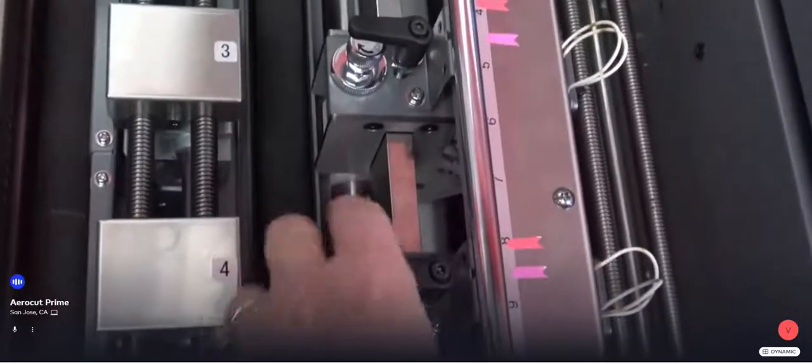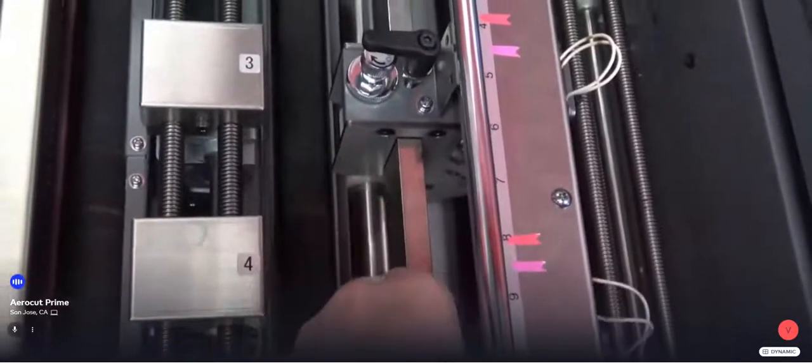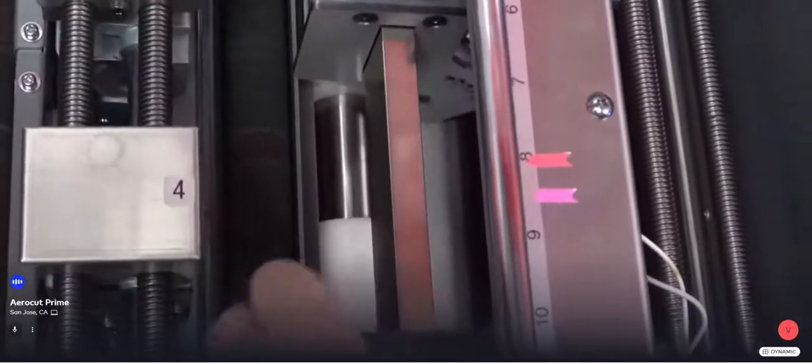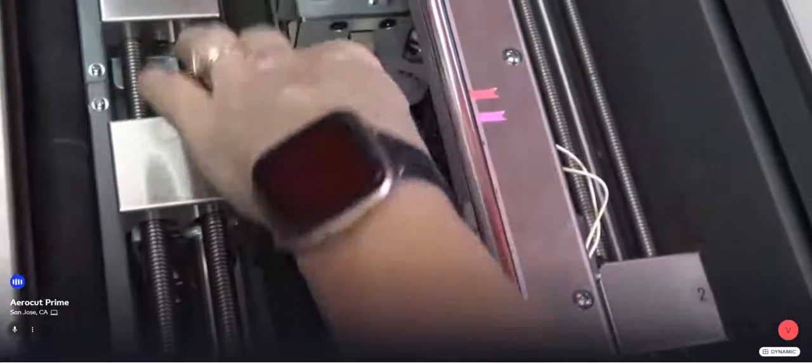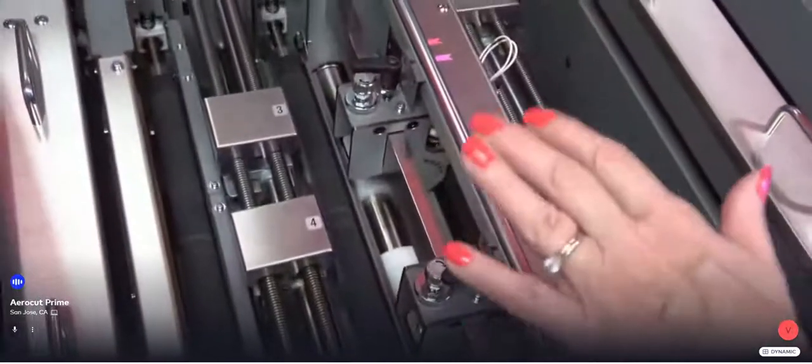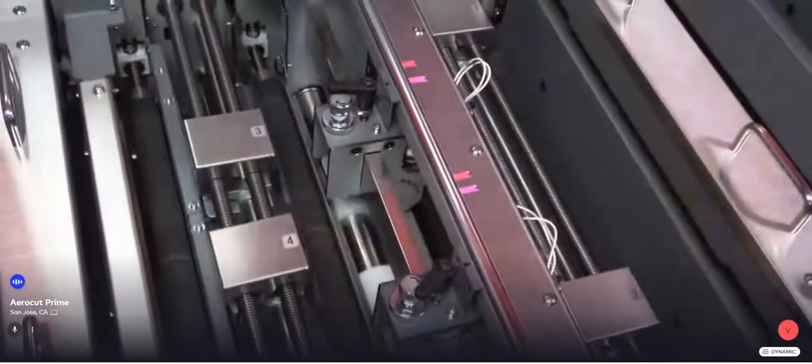If you move the unit in a way that it no longer aligns with that, like let's say your perf unit was over here at 10, for example, it would no longer line up with this plastic wheel here. So you would actually need to remove this and move the plastic wheel, because that's what adds pressure to the paper in order to perf. We do have a video on our website, and I think also on YouTube, that actually shows the process of how you adjust the little plastic wheel.